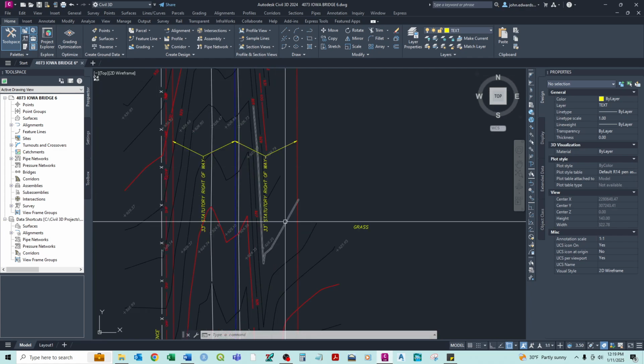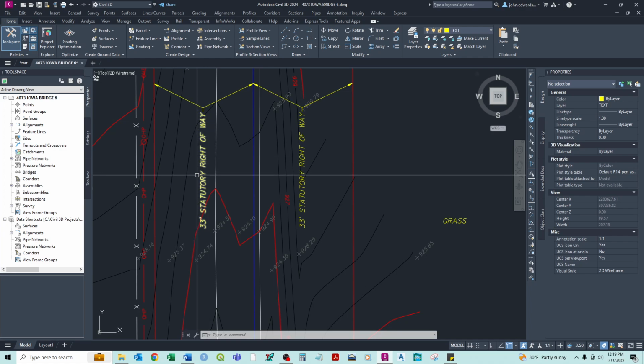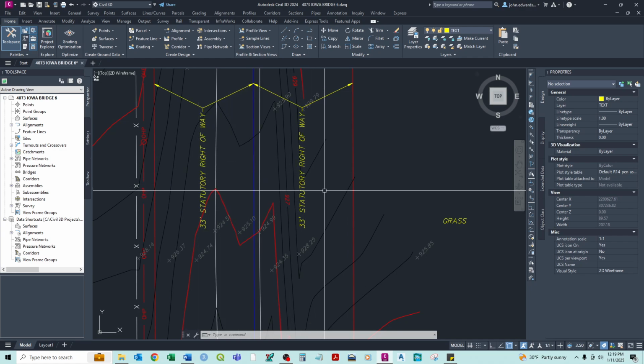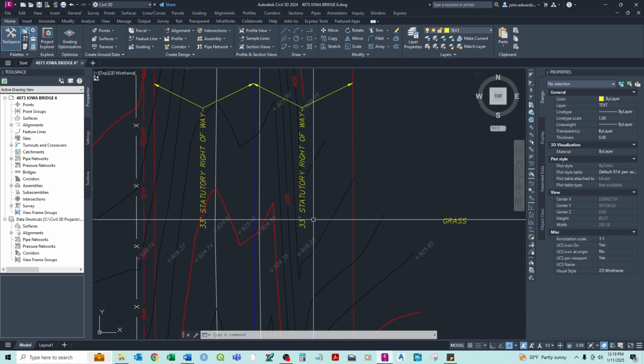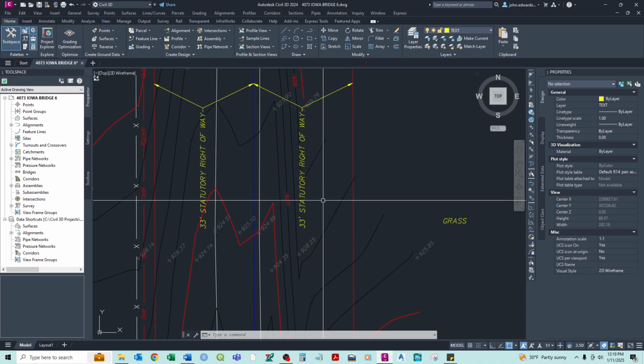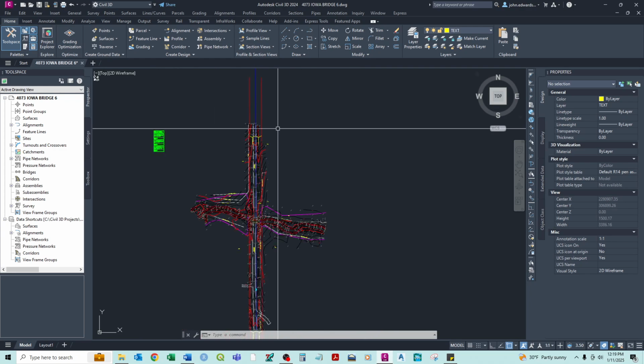And then last thing, he'll normally also put in the statutory right-of-way, which does vary between different counties and different regions of Oklahoma, so just keep that in mind. Most of eastern Oklahoma is 24.75, but over here it's 33. So that's somewhat helpful if we can put these roads back on section.